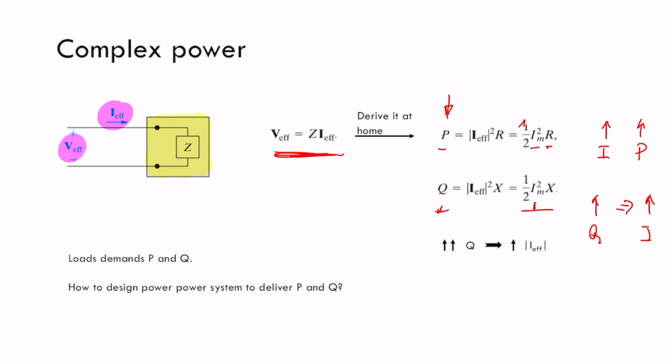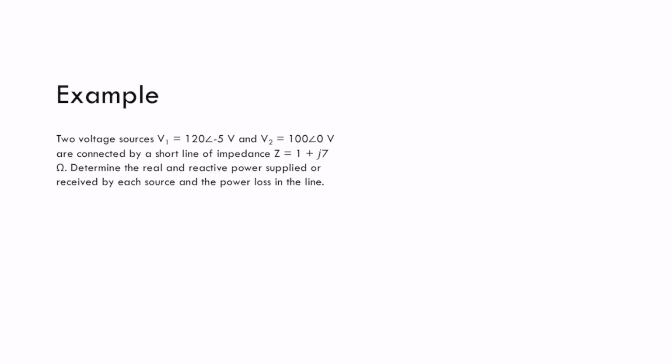The reactive power can also be delivered, but then you are increasing the current needed through this line, and also increasing the losses, because the current increases and then the active power loss also increases. So if I can design my system, I will prefer to have reactive power produced locally.